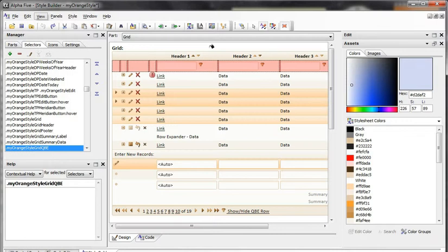It also can copy appearances, which you can do by holding down the control key. So in this instance we're going to hold down the control key and click on the grid header, and what has happened is we've copied the style from the grid header to the style appearance buffer. And if we go down to the footer and we let up on control, we have the paint bucket, and we click, what's happened is we've just pasted from the style appearance buffer into the footer.